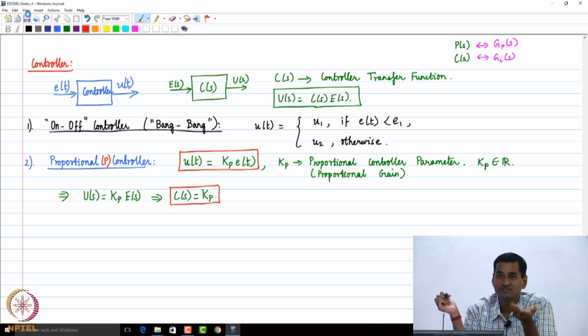By and large, this is the first controller we try out. When we want to design systems, if you see that the plant transfer function is of a certain structure, proportional control will work out most of the time. We are going to learn what tricks and characteristics we need to look for as we go along. By and large, the proportional controller is very effective, and very simple in structure also.